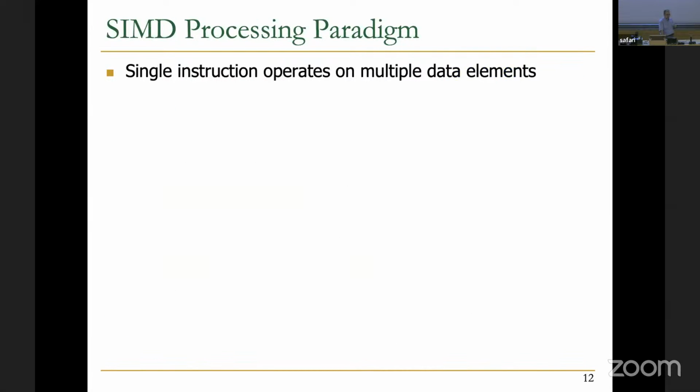So this SIMD processing paradigm is a single instruction operating on multiple data elements, and it can be in time or in space, like a duality. We have seen this a bit before: parallelism in time can be considered like the pipeline processor, which Frank taught nicely. Whenever you check your system at a single cycle, you're going to see that you are operating on different things.